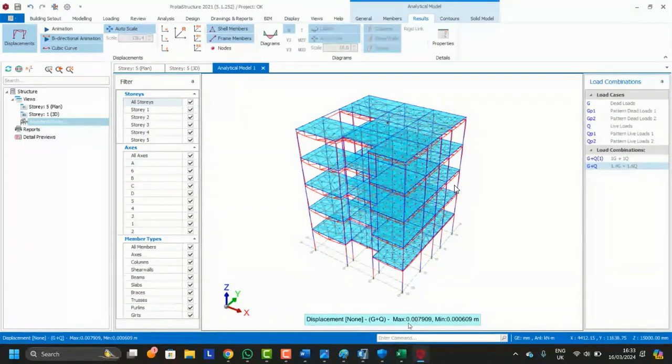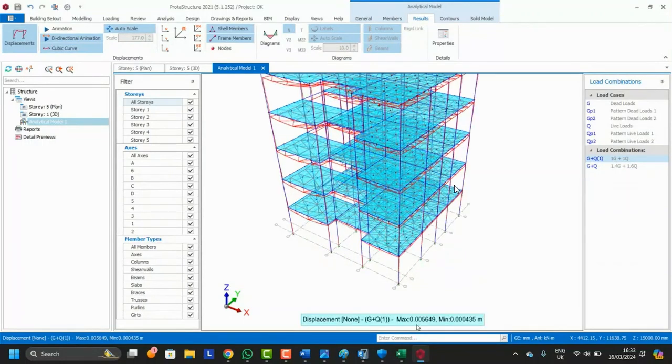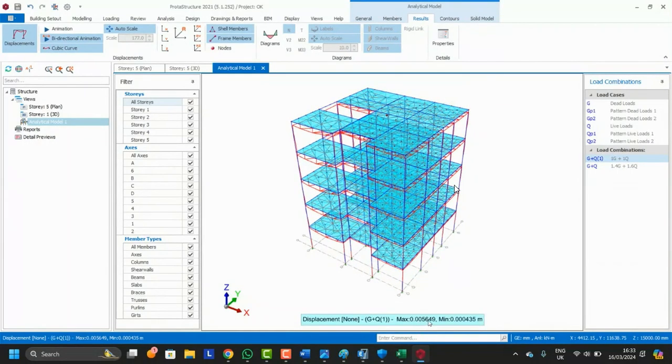But now we have made a mistake. Never check the deflection using the ultimate. As you can see here, this is a mistake. Don't check your limit state using this. Please be checking using serviceability. I think I discussed this one with some of you. So right now, as you can see, it acquires 5.64.